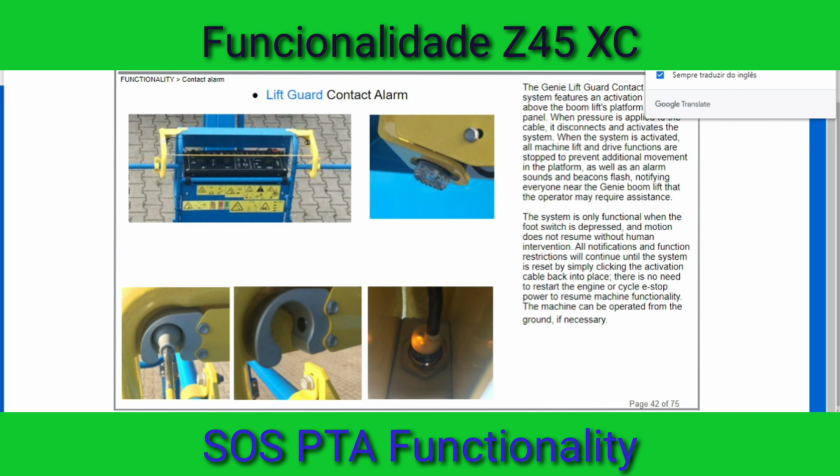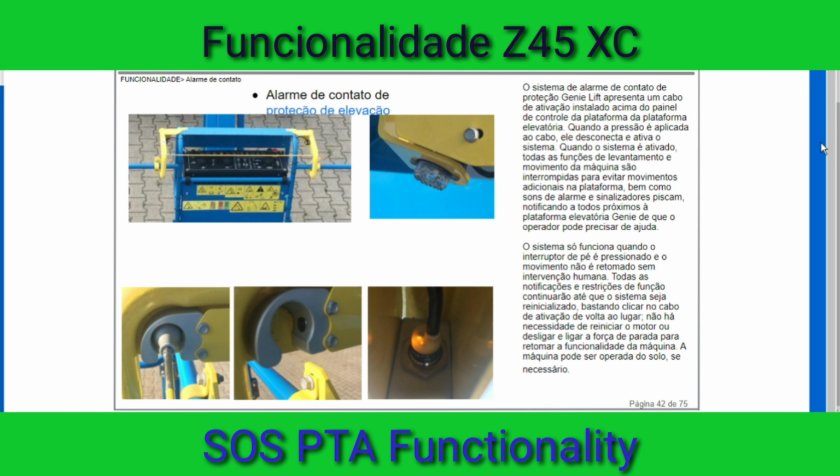The GENIE lift guard contact alarm system features an activation cable fitted above the boom's lift platform control panel. When pressure is applied to the cable, it disconnects and activates the system. When the system is activated, all machine lift and drive functions are stopped to prevent additional movements in the platform, as well as an alarm sounds and beacons flash, notifying everyone near the GENIE boom lift that the operator may require assistance.